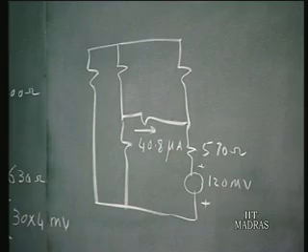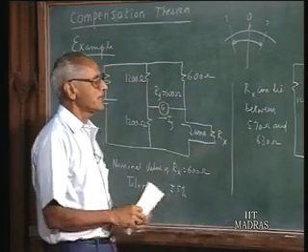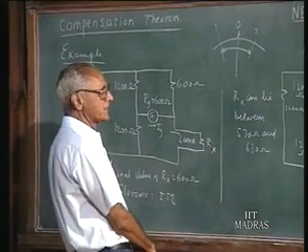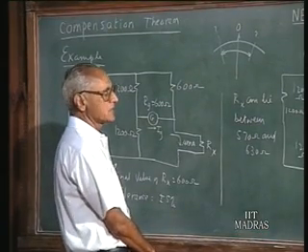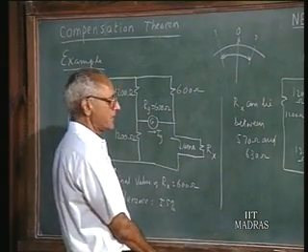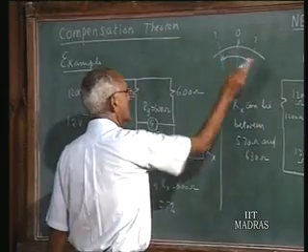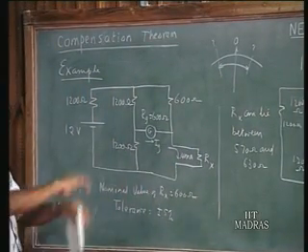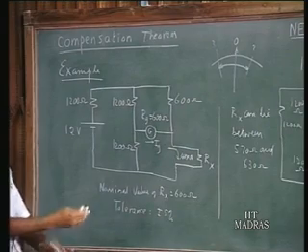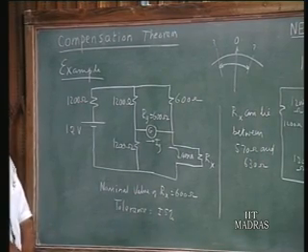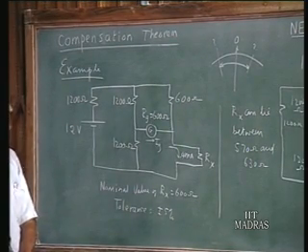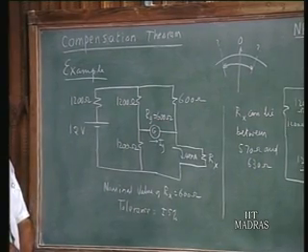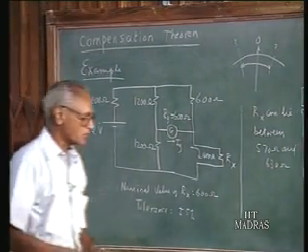So we can now say that the galvanometer current must be from 39.2 in one direction to 40.8 microamperes in the other direction. As long as the current lies within that margin, the resistance is between 570 to 630 ohms. If it exceeds that margin on either side, then the resistance goes outside the tolerance limits. So this is an illustration of the use of the compensation theorem in situations like this. Let's work out a second example.